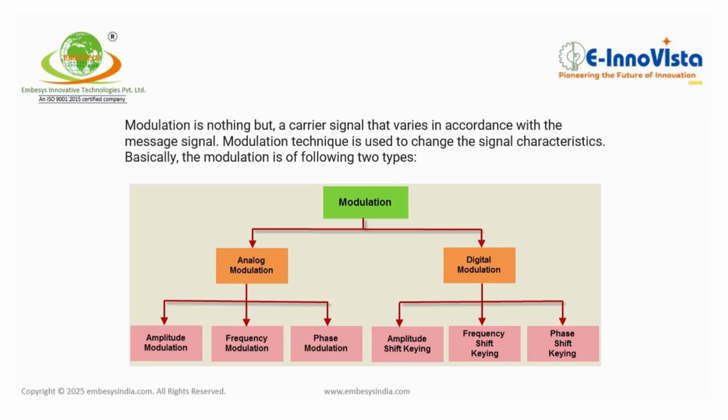And frequency modulation is a type of modulation in which only the frequency of the carrier signal is varied to represent the data, whereas the amplitude and phase of the signal are kept unchanged. And phase modulation is the type of modulation in which the phase of the carrier signal is varied to represent the data being added to the signal. It is denoted by 1 or 0, where 0 is represented by 180 degrees and 1 by 0 degrees.